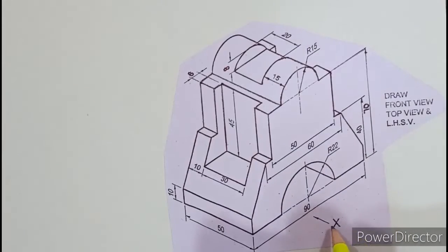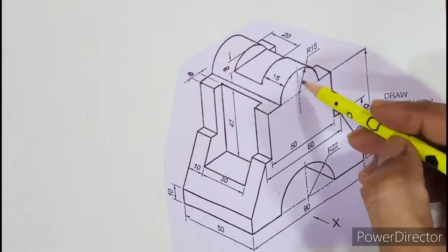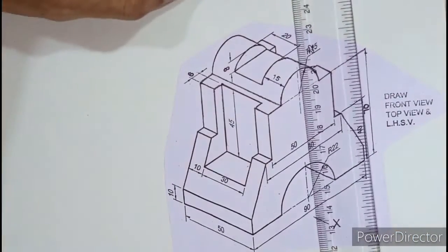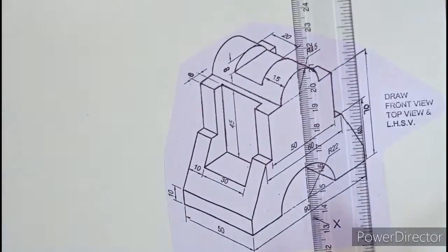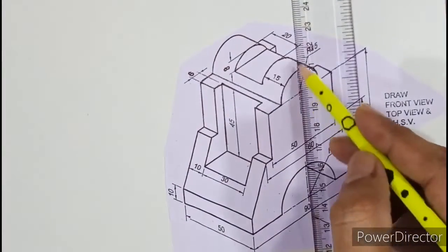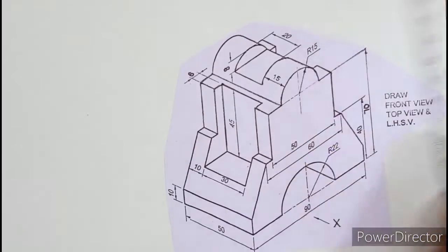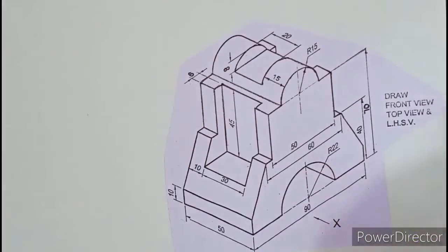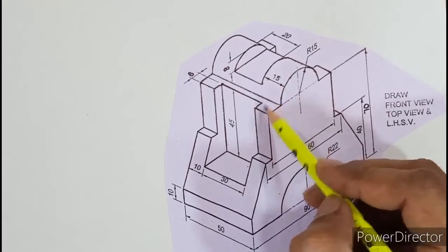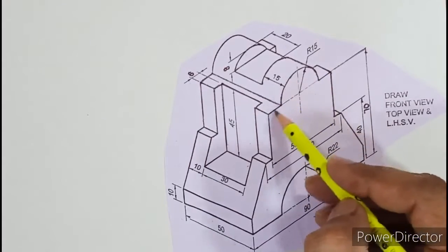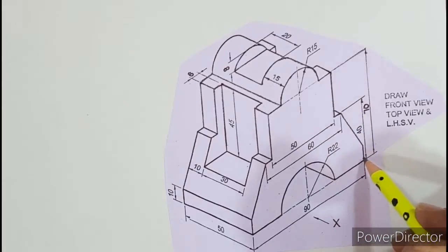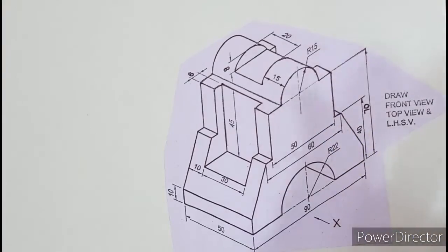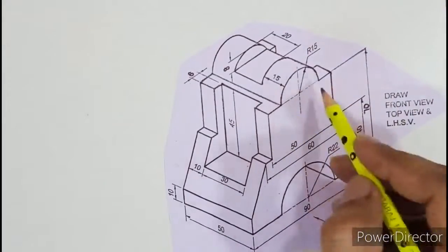After that, if you stand in the front position along x, you'll understand that if you look at this line, or if I keep a scale over here, you'll realize one thing, that in the front direction the object is symmetrical about this vertical line. It is same on both the sides. There is a cutout on the left side, same cutout is there on the right side also. In the photograph it is not very clear what is there on the other side, but whenever you find such similarities on the left and the right side, you have to assume that the object is symmetrical and the same cutout exists on the other side also. That will be your assumption. Always assume like that if it is symmetrical.